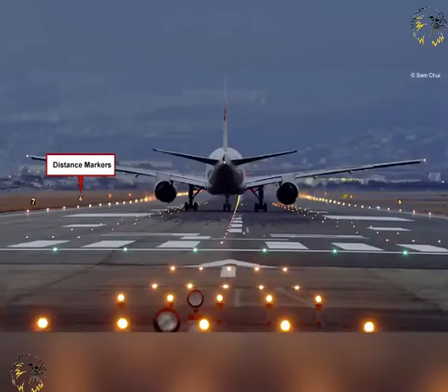Runway length is reported in meters. However, fixed distance markers are placed along the edge of the runway 1,000 feet apart, starting 300 meters from the threshold. For a paved runway to accommodate instrument approaches from either end, it must be at least 1,800 meters between thresholds.